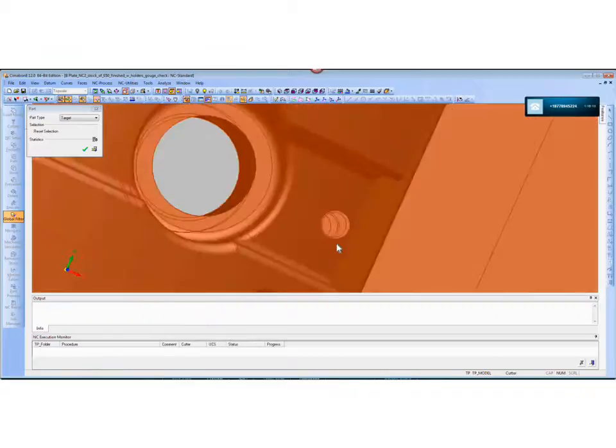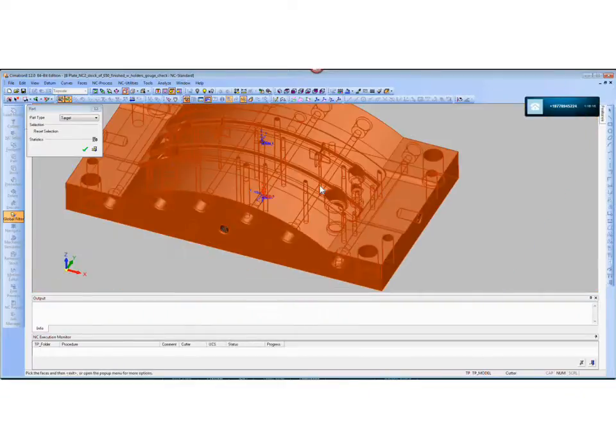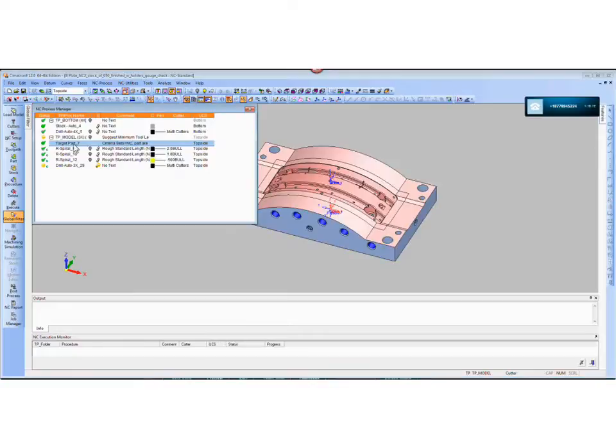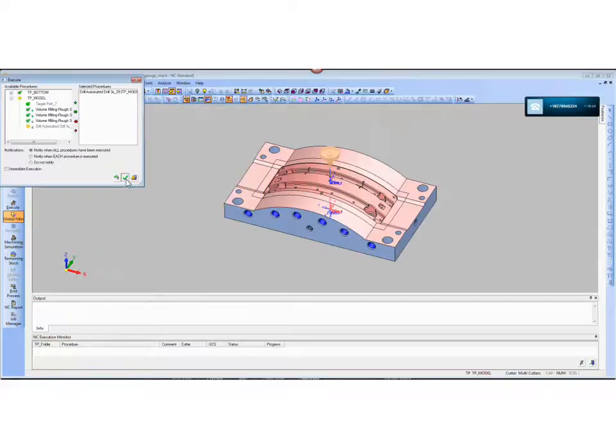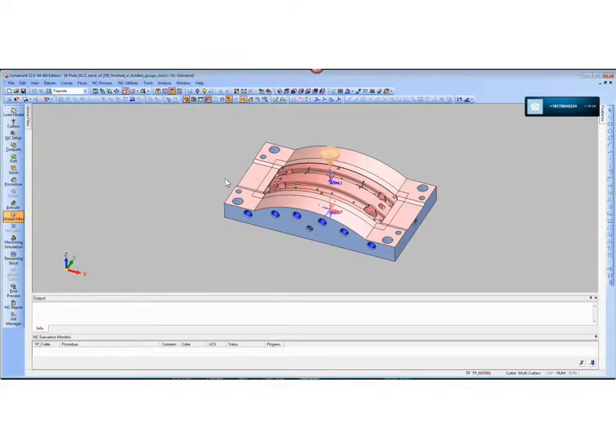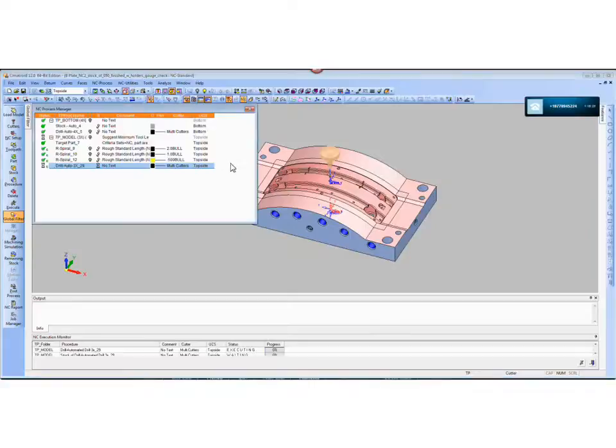All right, so I'm going to go ahead and execute this. And we should get an error message. And actually, there's going to be two error messages. This one may not be a problem now. It'll be a problem later when I verify it. But I know I'm going to have an issue where the 1/8 drill was not able to process this hole. Okay, I get this little interrupted symbol here. That interrupted symbol tells me to come down here and look for what's wrong.